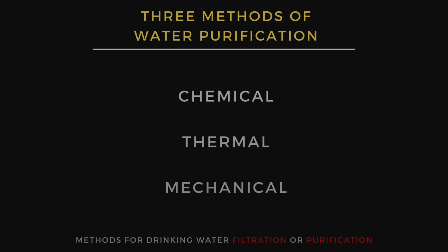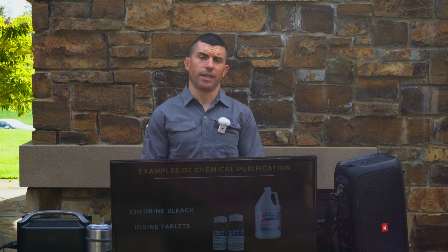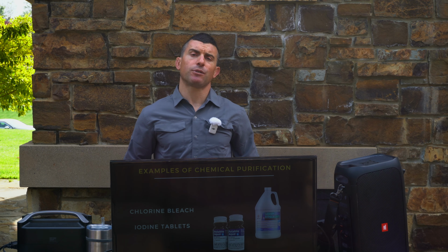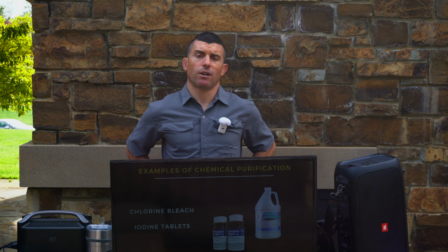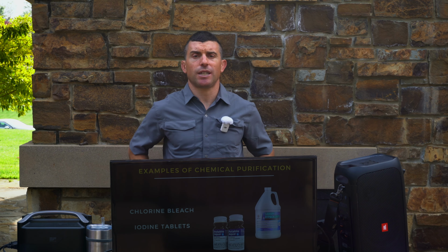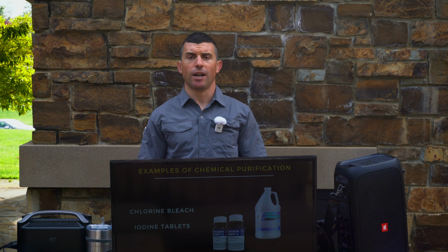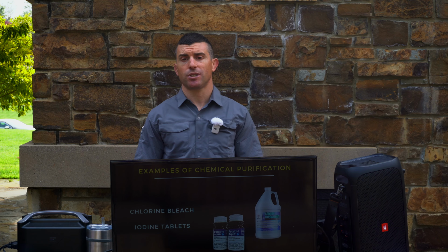Now, water purification is generally either going to be chemical, thermal, or mechanical. You also have UV for purification. So at this point, we're talking about killing the water, not cleaning the water. Cleaning the water is what we would have done in our filtration stage. Killing the water is what we're doing in a purification stage. We're making the water free of the bacteria, of the protozoa, of the viruses.